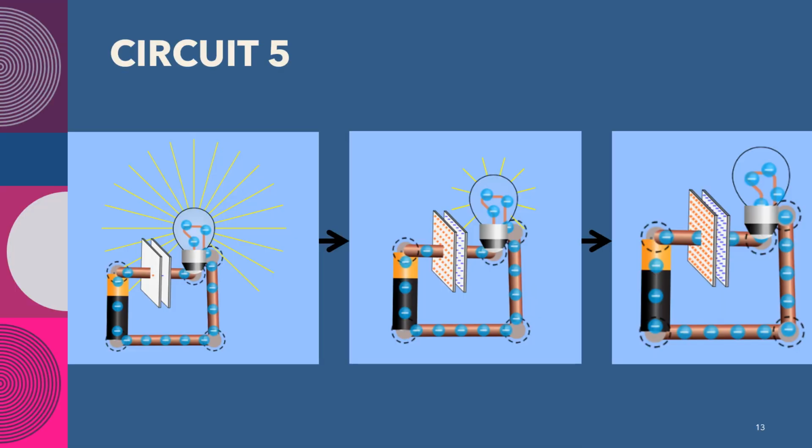Here we see what happens when we add a capacitor. We can see the capacitor building up charge, and as it builds up charge, the current flowing through the wire decreases, as seen through the decreasing brightness of the light, until it eventually goes out. The time it took the capacitor to charge with a 10 ohm resistance bulb, a 0.2 farad capacitor, and a 9 volt battery was 6.24 seconds measured, and the discharge time was 6.69 seconds.